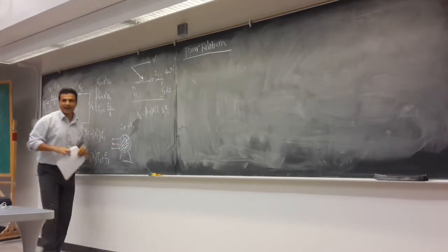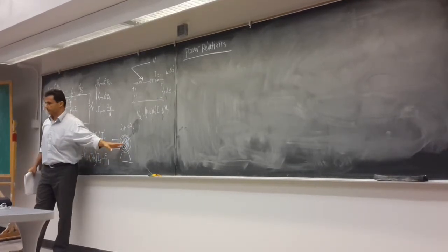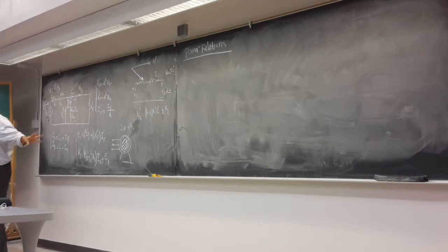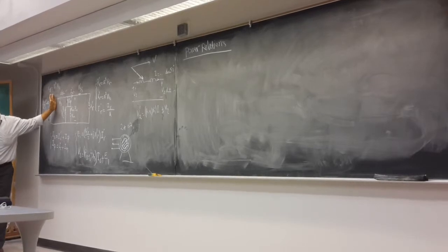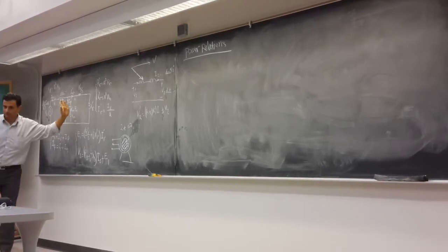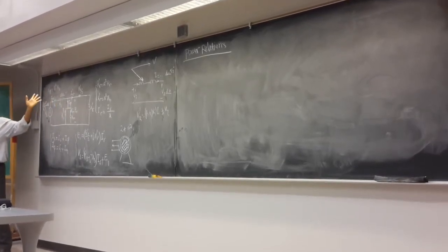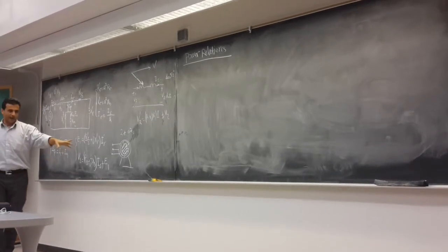They call it air gap power, or P gap. So basically, P gap is going to be P in, let's call it here P in, the power coming to the machine, minus the stator resistive loss, minus the stator core loss. They call it machine core loss. So we are going to have P gap.